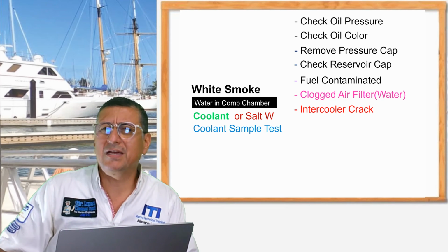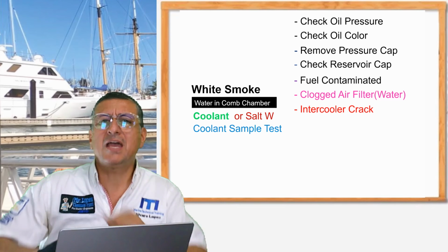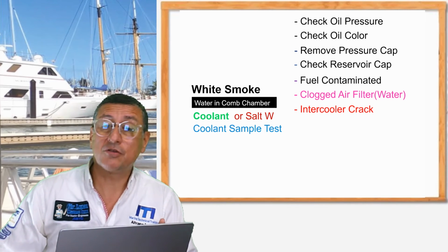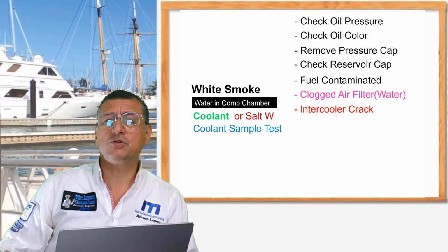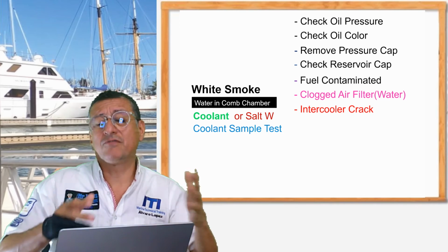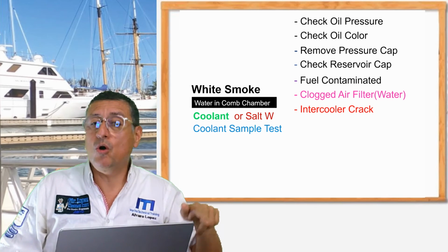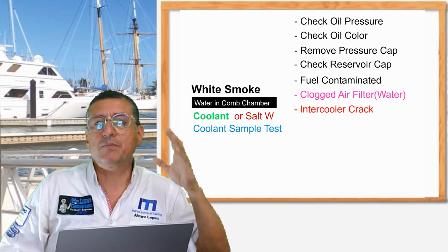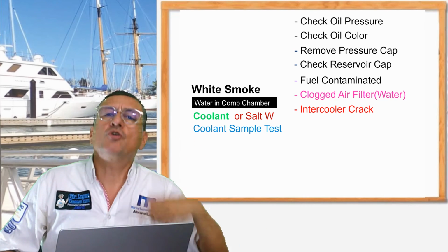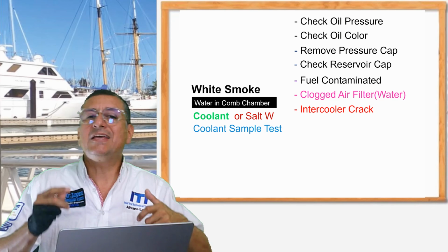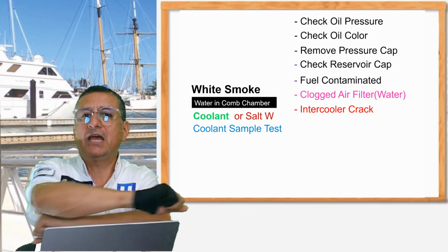Remember that when salt water enters the combustion chamber, practically immediately the engine locks. In comparison, when coolant enters the combustion chamber, of course, at the end of the day the oil will be milky, but the engine continues running with low oil pressure, because the coolant damages the properties of the oil and the oil pressure decreases dramatically, but the engine continues running. However, when it's salt water entering the combustion chamber, in a couple of seconds the engine locks.